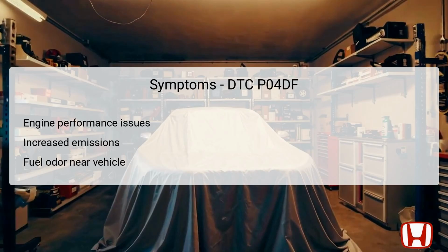This might also lead to a visual inspection revealing a fuel odor near the vehicle, particularly around the fuel tank area. Such odors can signal an impending issue with fuel vapor management, alarming the driver about potential environmental hazards or regulatory concerns. Monitoring these symptoms is crucial for timely diagnosis and repair.